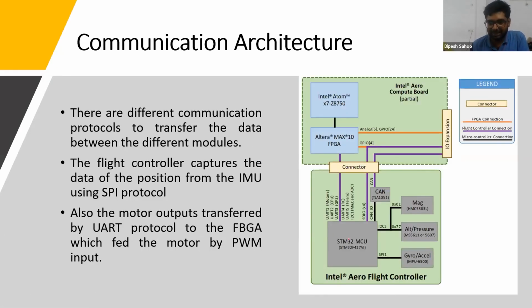There is no directly PID controller. You can say PID controller is actually a mathematical architecture. That architecture is uploaded to the flash memory, and the processor calculates the outputs based on those architectures.